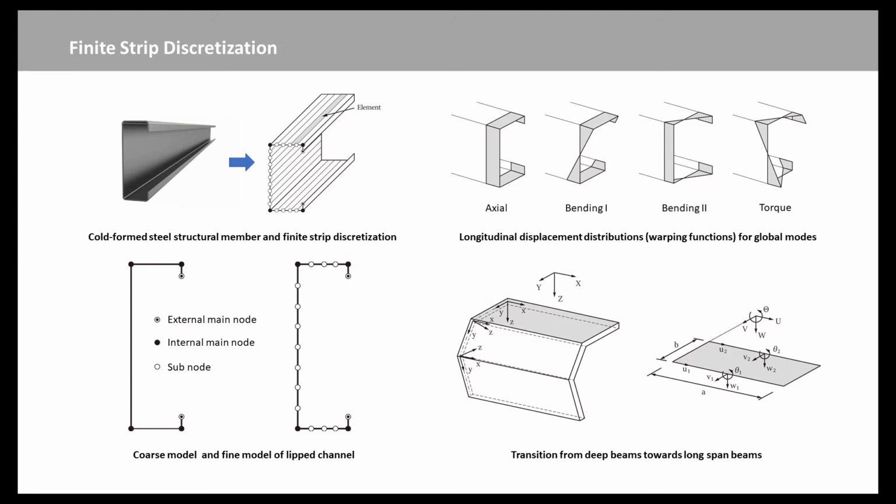In the local coordinate system associated with each strip, the corresponding degrees of freedom are the translation small u in the x direction measured at the specimen ends, as well as the translations small v and small w in the local y and z directions, and the rotation small theta about the x-axis, all measured at mid-length.